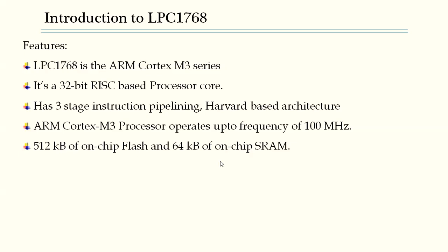The programming of this flash memory can be accomplished in several ways. It may be programmed with in-system programming via the serial port, and that's what we have with the LPC1768. And the application program may also erase and program it while the application is running, which allows a great degree of flexibility for data storage and field firmware upgrades.